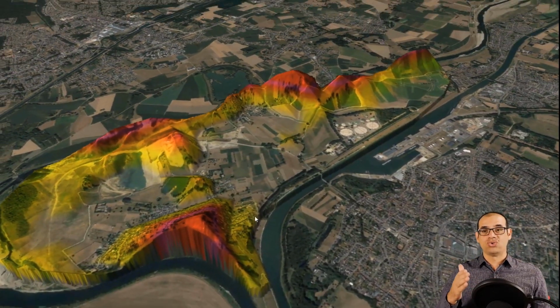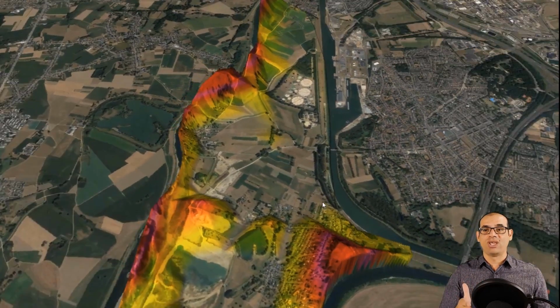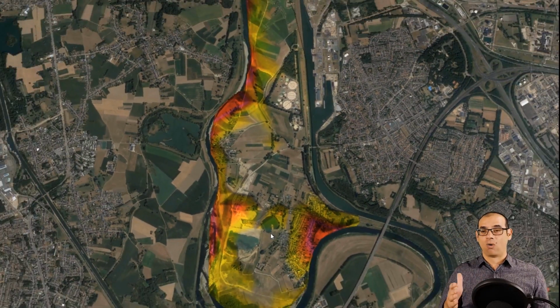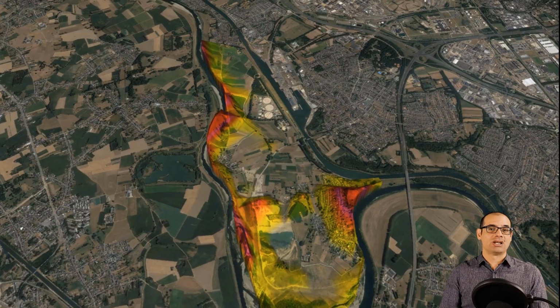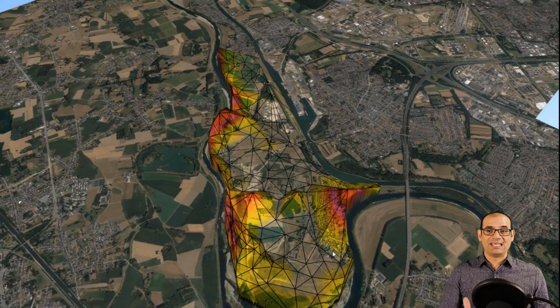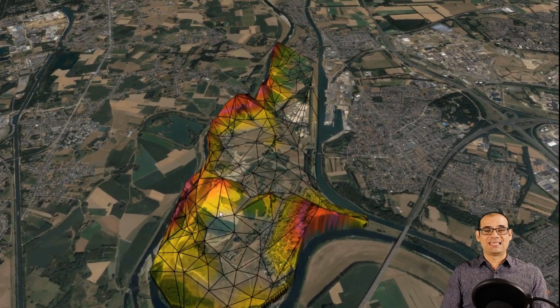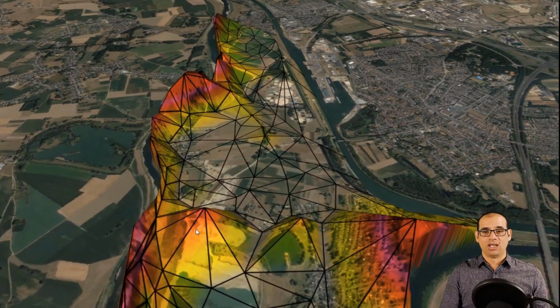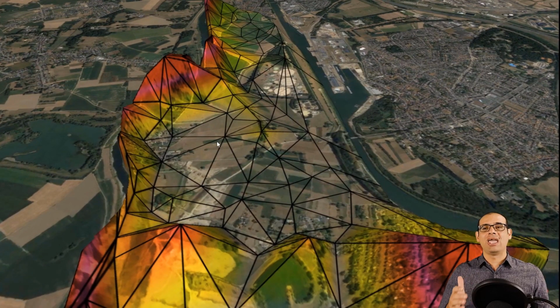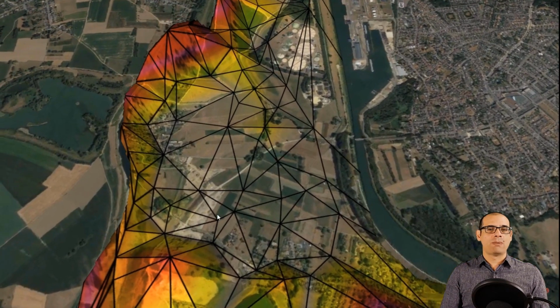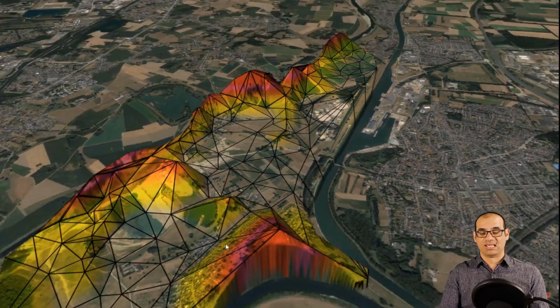What we are going to do today is a 3D surface where the coordinates x and y represent a two-dimensional plane and the z coordinate, that is the variable of interest, is the third dimension, and in this case it is the zinc concentration. The surface is going to be created with triangles, and each vertex of these triangles is going to be a sample of the measurements. The values of the pixels inside each triangle are going to depend on the three closest vertices.